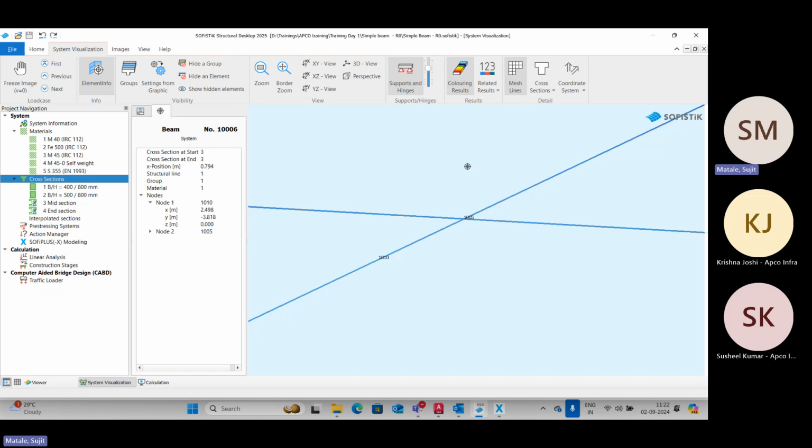Just draw in appropriate planes the vertical element, the plate element, and the pile elements. I have those models already ready. I can show you. You don't need to be worried about your nodes and all that. So that really helps a lot. Column can be a single line element. Yeah. Footing can be a plate element.